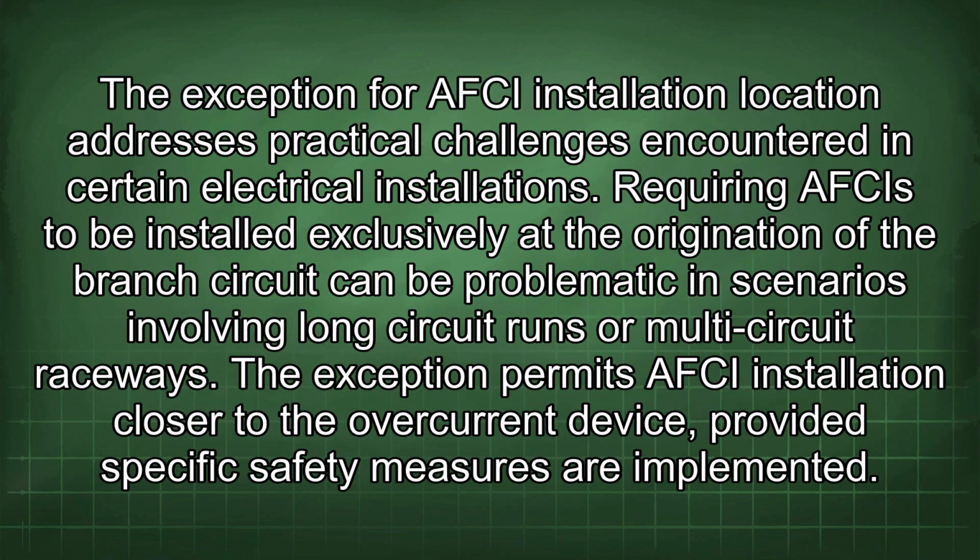The exception for AFCI installation location addresses practical challenges encountered in certain electrical installations. Requiring AFCIs to be installed exclusively at the origination of the branch circuit can be problematic in scenarios involving long circuit runs or multi-circuit raceways. The exception permits AFCI installation closer to the overcurrent device, provided specific safety measures are implemented.